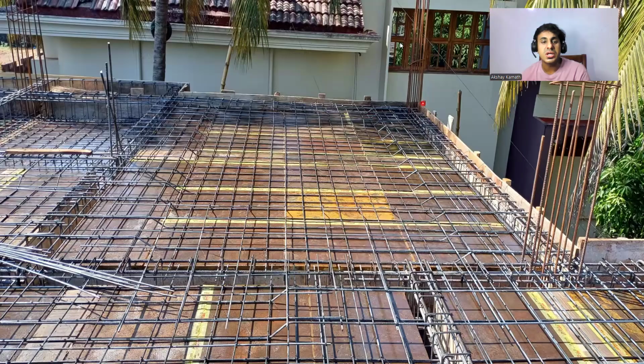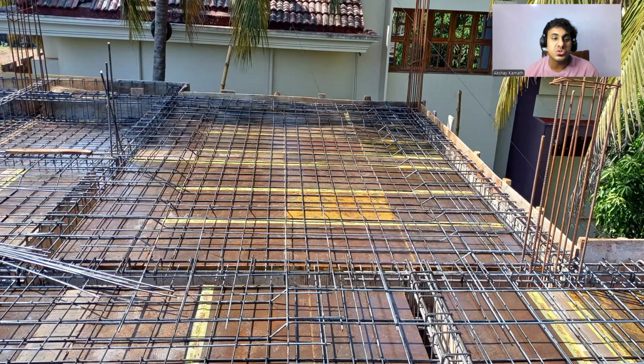Now, if I ask you, can you correlate all these things? Exactly. See, I have a beam here, a beam here, a beam in this direction, and a beam in this direction. And in between that, I have a slab. Now, if I ask you to draw the bending moment diagram of this, or show what the bending moment of this is, this portion will try to lift up. It will try to go down, sagging, and a negative bending moment. So that is why you can see the top steel has been provided here. If you see here, I'm providing a top steel like this.